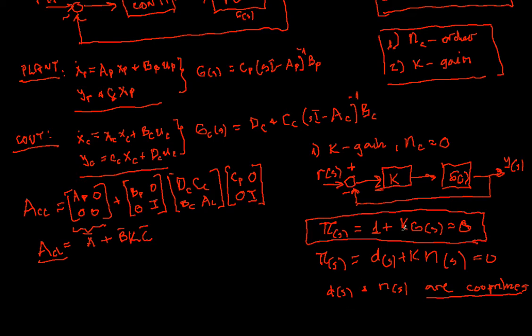Therefore, for a given gain, you fix the gain, you solve the characteristic polynomial, and one obtains in the complex plane the following distribution of the eigenvalues. Let's say one pair of complex conjugates and one is real. So this is lambda 1, this is lambda 2, and this is lambda 2 conjugate. In other words, as the gain K is changed,